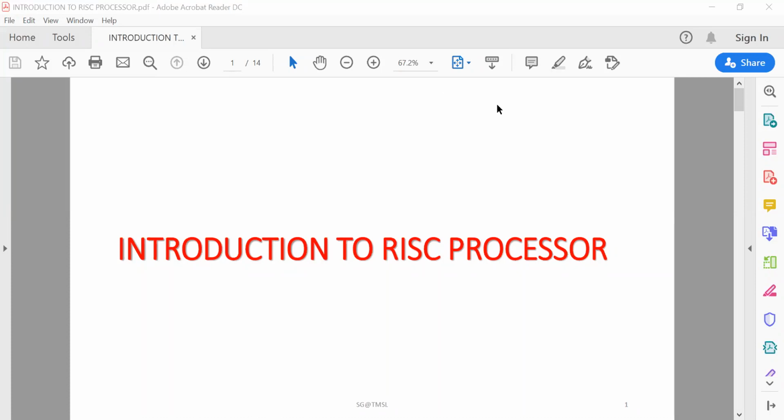This large die size in turn means more cost, since it consumes more silicon to fabricate the processor. Also, as the chip size increases, the power consumption also increases, resulting in more heating of the chip, which in turn requires more cooling arrangement.